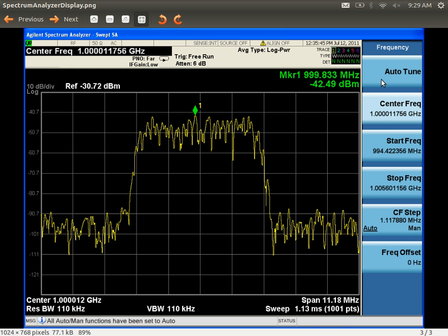But we see most of the energy because this axis shows us the peak signal strength. Ignore the units, but we see, okay, the signal is strongest within this frequency range, within this spectrum. And in fact, very weak in this area. So we could consider the bandwidth of this signal ranges from this point up to this point. So this is a capture of a real signal that was transmitted across some wireless link.